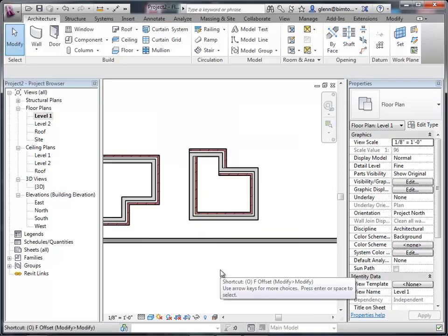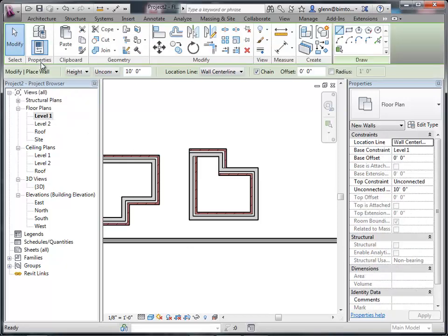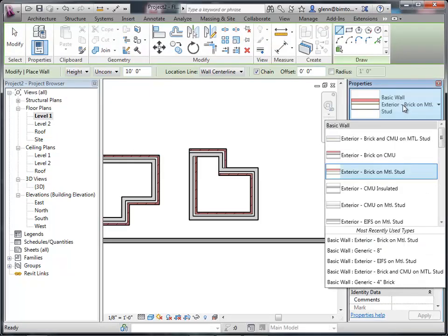Here's basically the deal with the walls. As you're working with walls, you get this nice list of all these different wall types. But if that doesn't look like the type of walls you want, here's what I want you to do. Go through that list and find the one that's probably closest to what you want, but not quite right. Stud wall, stucco, I don't know. Let me go for brick on metal studs. Maybe that's close. It's not real close, but it's a start. Let's take a look at how that wall is defined.